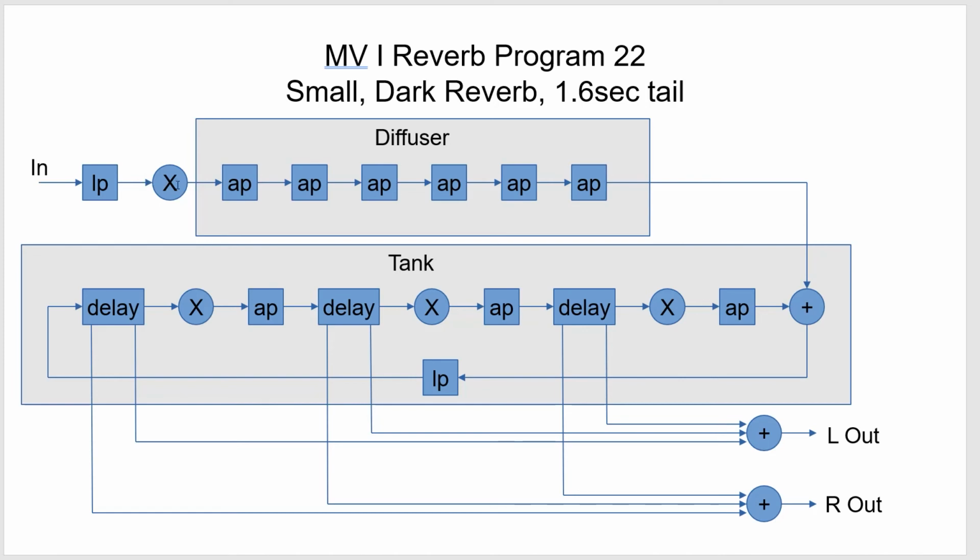So when he does the math, he tries not to overflow. And it goes through 6 all-pass filters. And each one of these all-pass filters has a different cutoff frequency, or we call it a center frequency. And this was all done empirically. And these range, in this particular stage right here, I believe from about 60 hertz up to about 200 hertz.